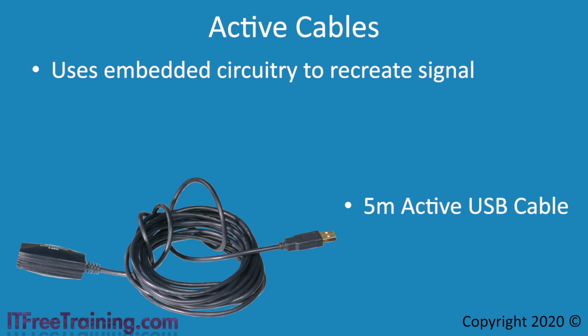Some cables will not be as obvious as this one. With some cables, the electronics will be inside the plug. I will have a look at such a cable later in the video. An active cable can increase the possible maximum length of the cable. For example, you will find that with an active cable, the length may be increased to be even longer than the maximum specification allows. If you need to purchase a cable longer than the maximum specification allows, make sure it is an active cable.